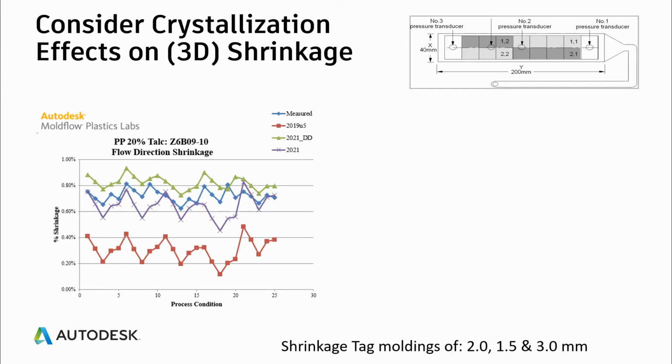It's worth mentioning at this point that this new enhanced crystallization effect will typically increase the shrinkage predictions for those semicrystalline materials which are sensitive to this effect. Let me stress, not all semicrystalline materials will be showing this effect, but the ones that are affected by this change will typically show an increased shrinkage prediction.